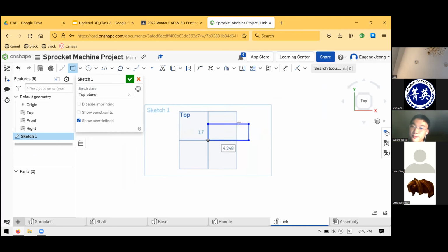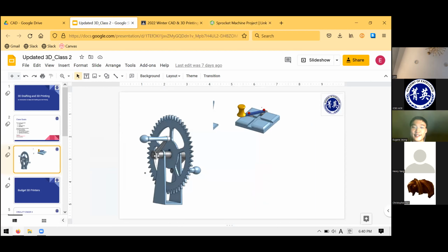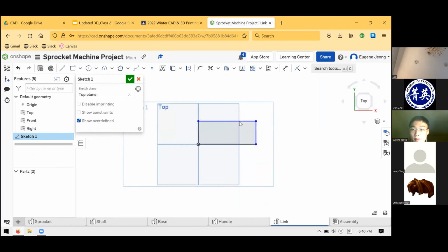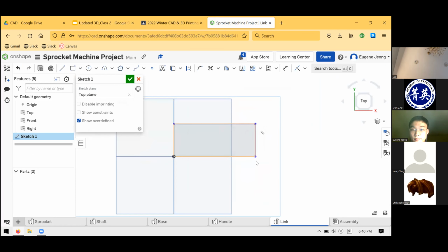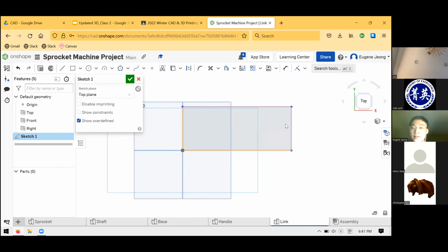So really, as I always say, what shapes do you see? I'll cut to the chase here. What I see that's important are these 2 circles. One circle where the handle goes on and another circle where the shaft goes on. So it has to be slightly bigger than the shaft. If you want this to slide over your shaft, you need some extra material around it.